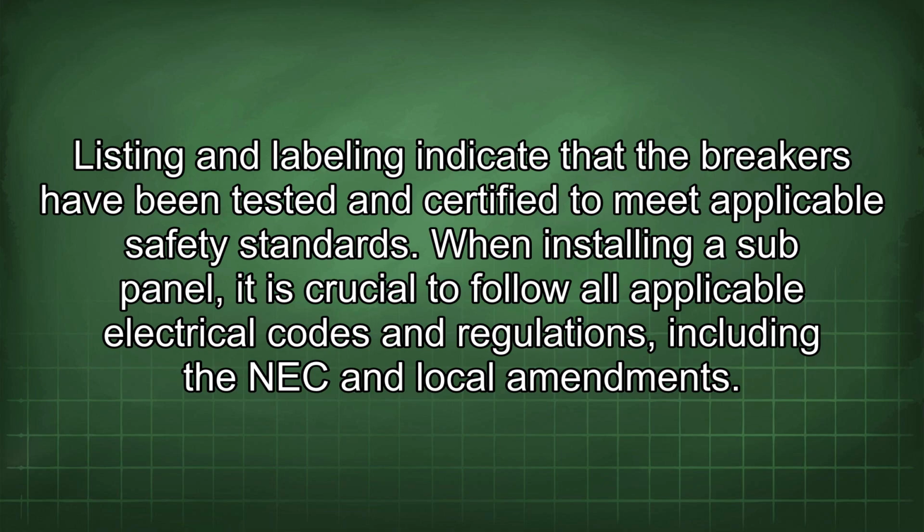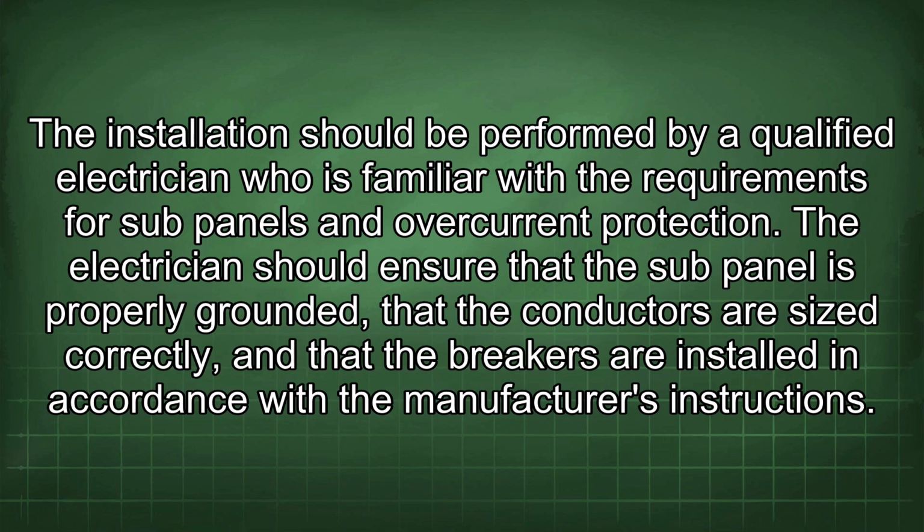When installing a sub-panel, it is crucial to follow all applicable electrical codes and regulations, including the NEC and local amendments. The installation should be performed by a qualified electrician who is familiar with the requirements for sub-panels and overcurrent protection. The electrician should ensure that the sub-panel is properly grounded, that the conductors are sized correctly, and that the breakers are installed in accordance with the manufacturer's instructions.